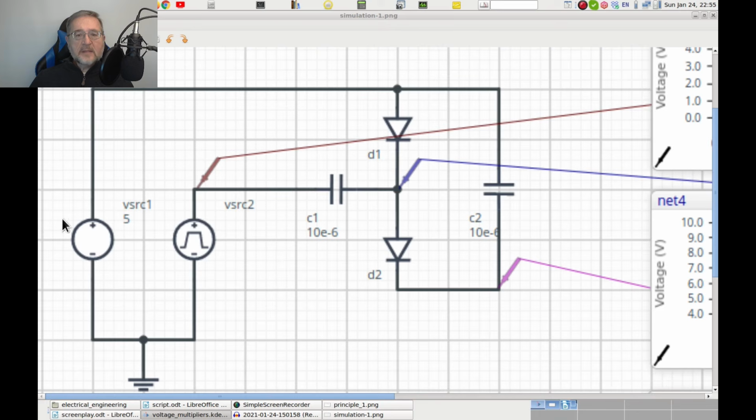I did that by replacing the battery and the switch with a couple of generators. The first generator, a constant voltage generator, provides the fixed voltage that we need. The second generator replaces the battery and the switch S1, providing a square wave going into the left lead of C1. In addition to that, I directed the simulator to continuously probe the voltage in three key points: the output of the square wave generator, the middle point between the diodes, and the output of the circuit, to generate the diagrams of the transient that happen in the first 2 seconds after the circuit is powered up.